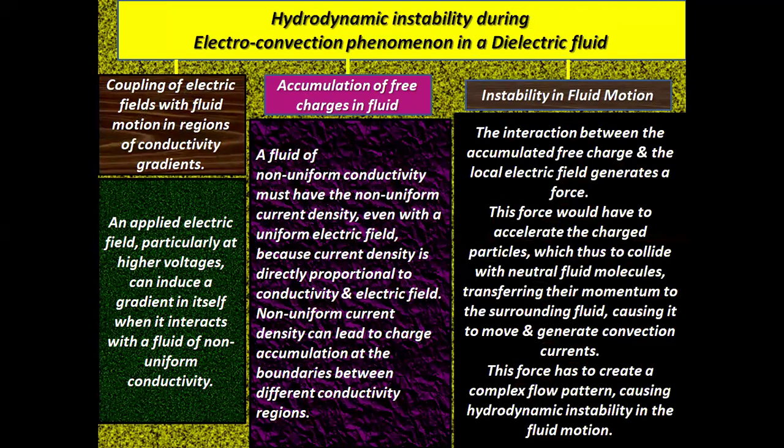Hydrodynamic instability during electroconvection phenomenon in a dielectric fluid: coupling of electric fields with fluid motion in regions of conductivity gradients. An applied electric field, particularly at higher voltages, can induce a gradient in itself when it interacts with a fluid of non-uniform conductivity.